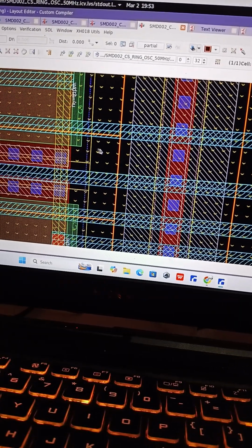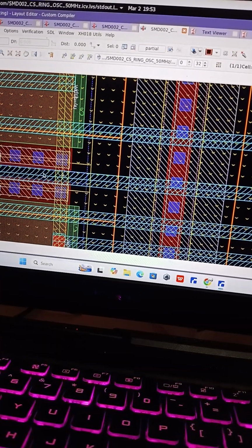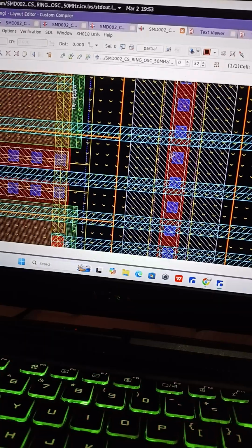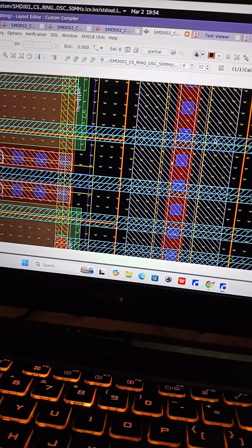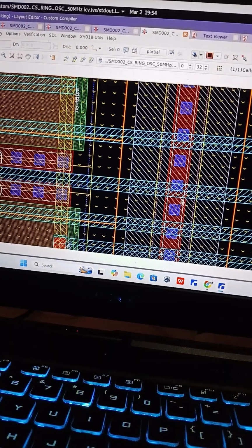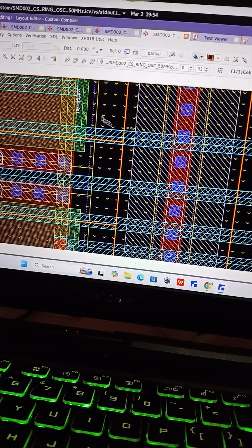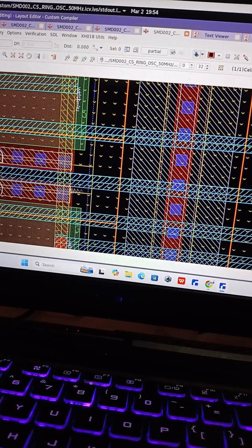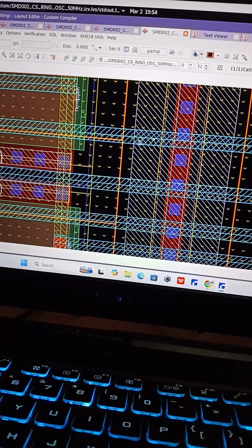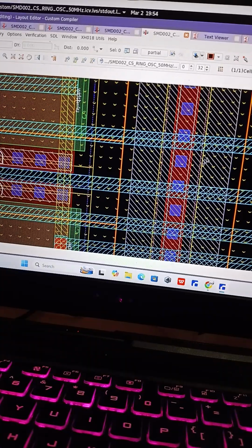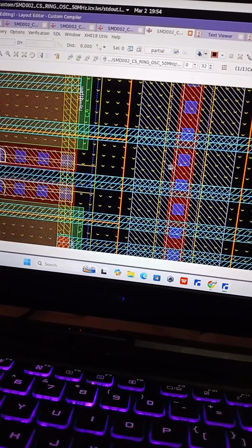We call it a parasitic capacitor. As you can see, this is a parallel metal plate, and this is a parallel metal plate. So there will be a current flow and a source, and when that happens there will be an accumulation of charge here and here, so an electric field is induced. That's how the parasitic capacitor arises, right?